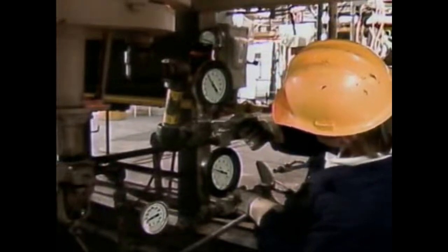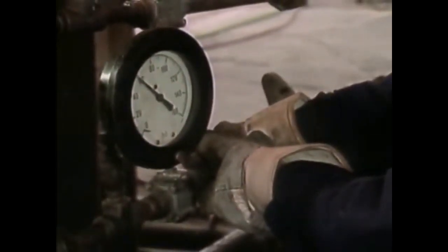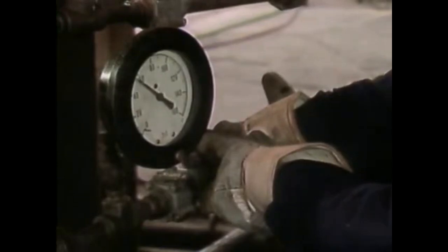With an oil burner, besides adjusting airflow, another way to manipulate the flame pattern is to adjust the atomizing steam flow. For example, by adjusting the steam flow to the atomizer, you can adjust the length of the flame. The fuel oil pressure to the burner can also be adjusted. If the fuel pressure is too high for the amount of atomizing steam and combustion air that's supplied, the result could be unburned fuel oil.